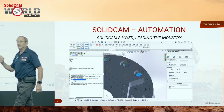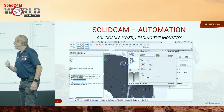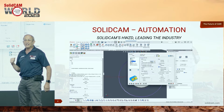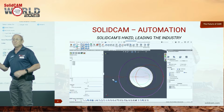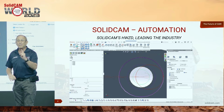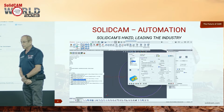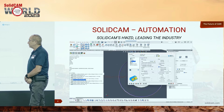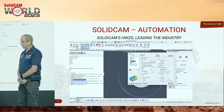Now, as far as the counterbore goes, that's a profile operation. There I've actually gone into the technology and used the delta information to modify my offset, always using the same geometry and keeping it associative to that geometry. And a lot of this stuff, remember, we're going to be putting more and more functionality into the feature recognition.